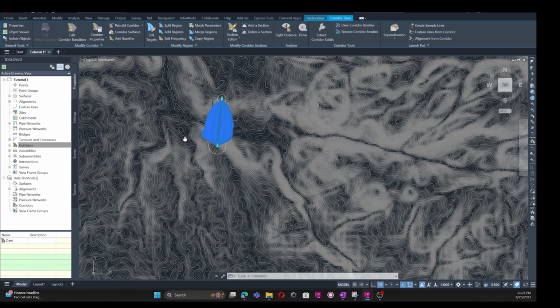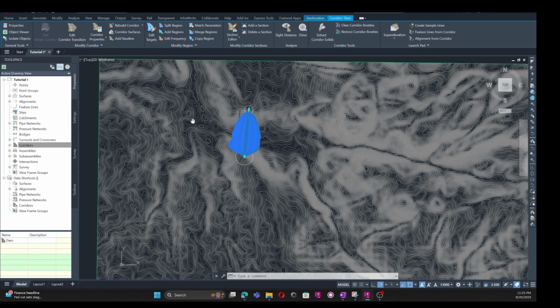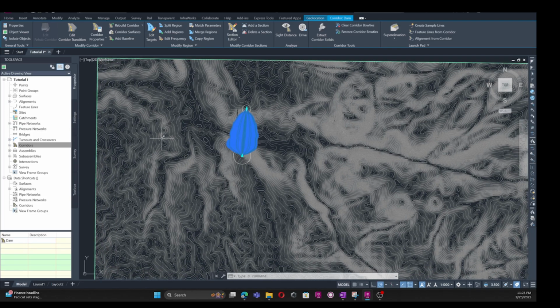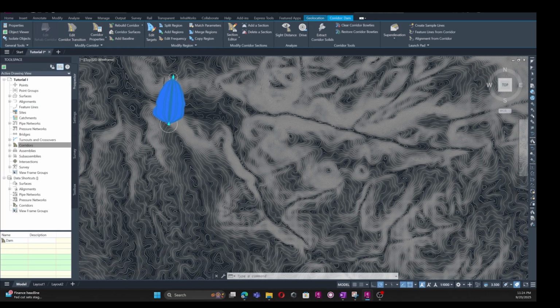To summarize, in this video, we started our design from scratch by geo-referencing our new project, importing a contour map which was saved in shapefile in a GIS environment, and using that we created our surface model of the existing ground.